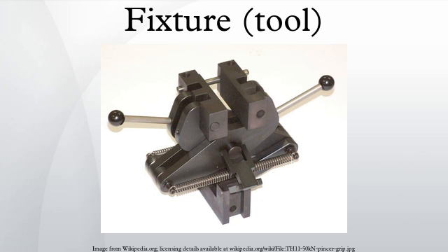Each component of a fixture is designed for one of 2 purposes: location or support. Location: locating components ensure the geometrical stability of the workpiece. They make sure that the workpiece rests in the correct position and orientation for the operation by addressing and impeding all the degrees of freedom the workpiece possesses.